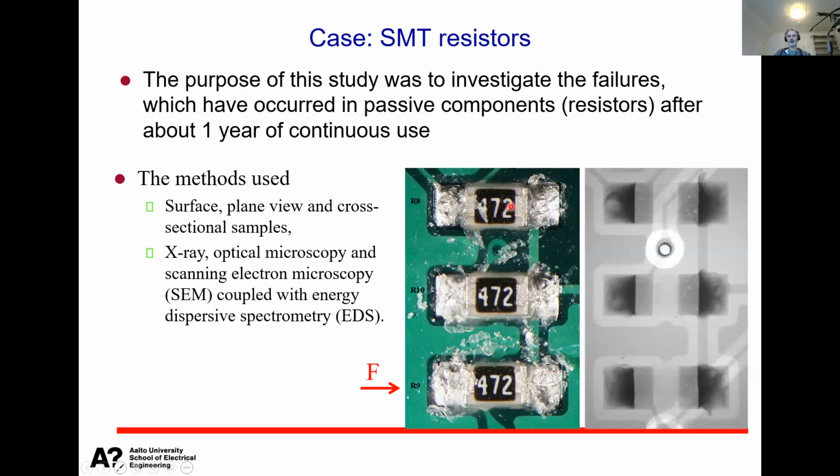component board, so the substrate and the components after the soldering, they were covered with this conformal coating. So basically everything was covered with silicone layer. And now in order for them to make the electrical measurements, so to really measure what is the actual resistance, they had to penetrate through the silicone. So that's the reason that you can see these silicone residues here. But this is just to measure from here to here the resistance, from here to here and here to here.